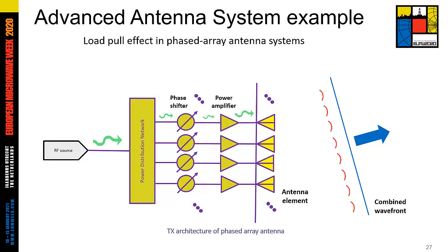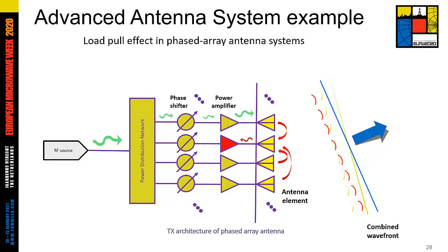The measurement campaign can be very time consuming and expensive, and sometimes calibration is not possible if we didn't anticipate some effects. Indeed, power amplifiers can be affected by the mutual coupling between each antenna element. In fact, this phenomenon on the antenna panel causes a load pull effect on each amplifier. This changes the characteristics of the circuits and then the signal magnitude and phase at the input of each element of the antenna. And so it changes the beamforming.